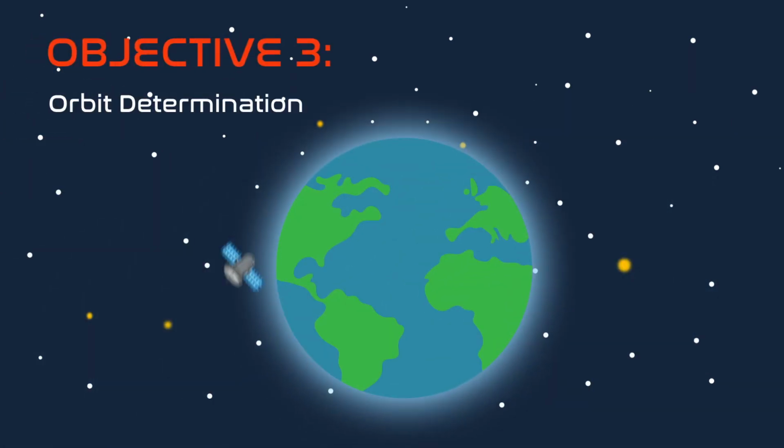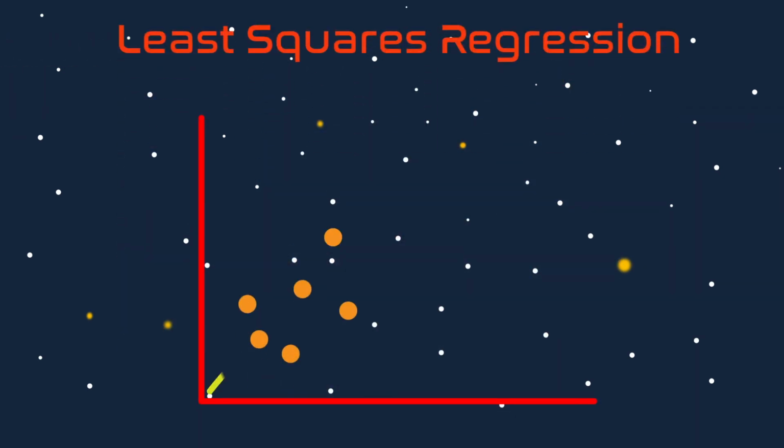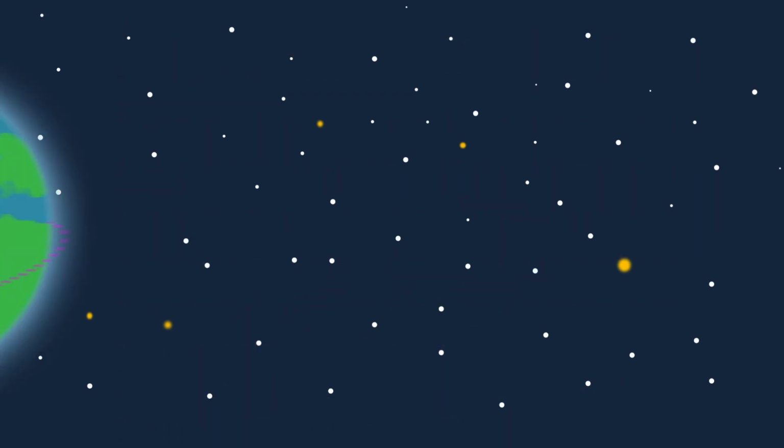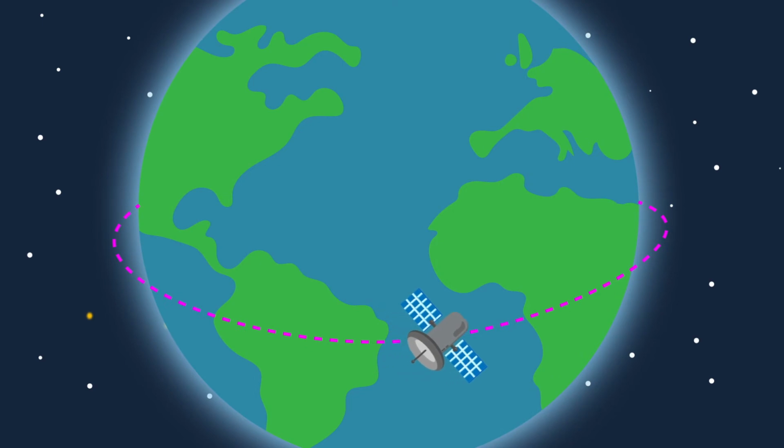After this, the next step is to conduct orbit determination. Using a least squares regression approach, an orbital state curve is fitted that best describes a sequence of detections within the tracklet set. The produced orbit determination results coincided with catalogue data.